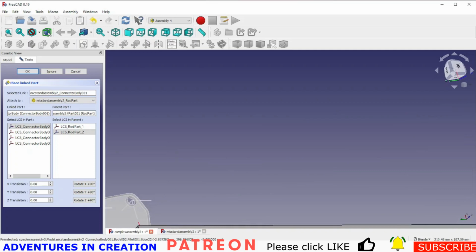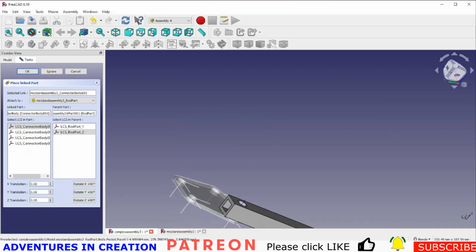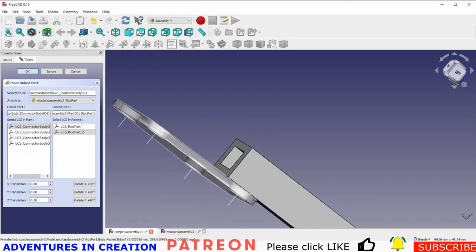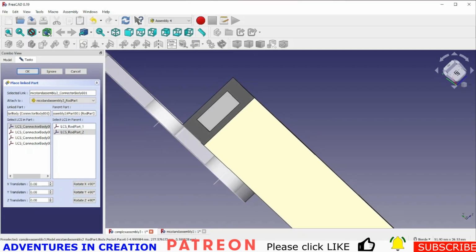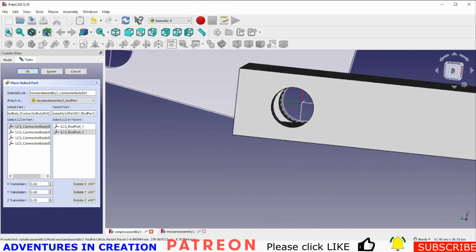And we're just going to look at the offset and make sure that the offset is correct, because we want to make sure that that plate is laying on the side of this one, which it actually is. So that's very good. If it wasn't, we can translate it right here. We can move it left and right to get it to line up. But that looks like it's lined up okay.